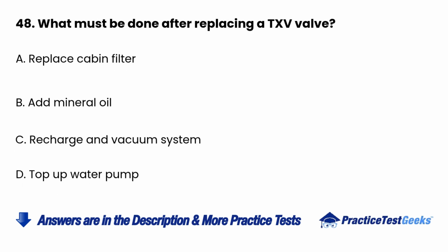48. What must be done after replacing a TXV valve? A. Replace cabin filter. B. Add mineral oil. C. Recharge and vacuum system. D. Top up water pump.